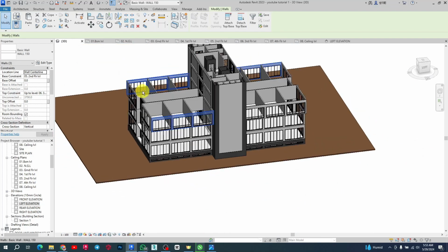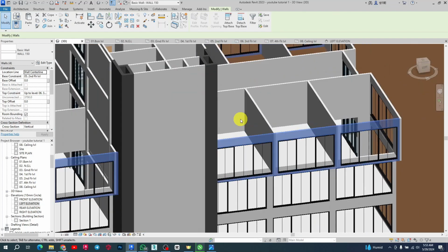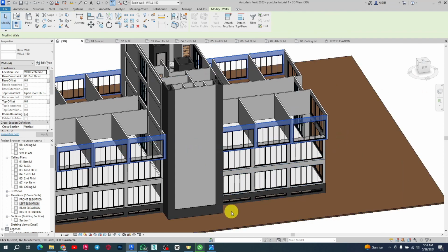So I'm assuming that the beam that will cover this is going to be, let's say, the base offset, right? I want to offset with the base. I want the beam offset to go down. I want the beam to be 500, right? 500 plus that 200 height will be 700, right? Because there's one block on top of it. But this cantilever beam, I can even make it 450, right? I can make it 450.